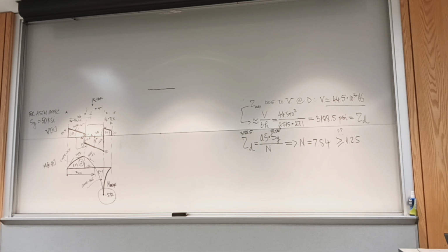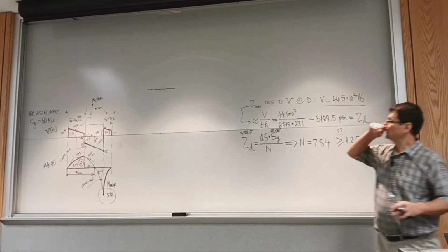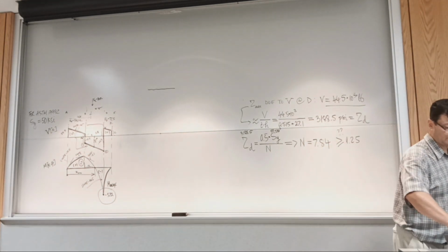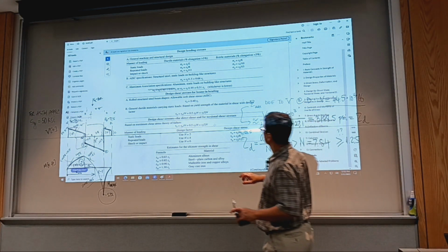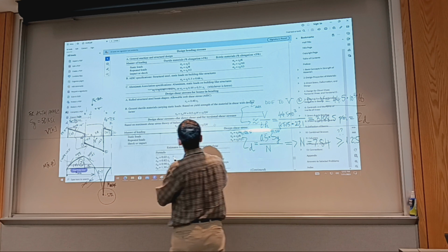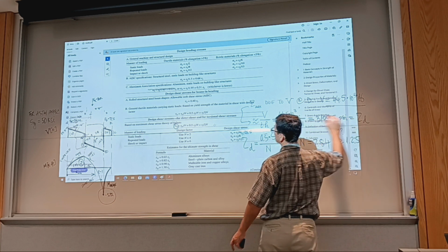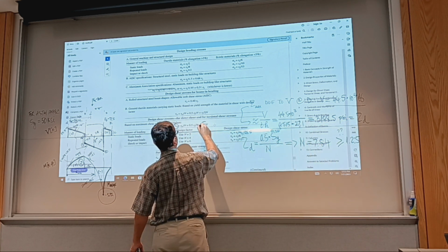So ours was structural steel, and this is the design stress for bending and for shear. For direct shear and for torsion shear stresses, this is the equation. So I made use of this equation. Oh, I'm not projecting. Come on, projector. All right, so design shear stress, direct shear, and for torsion. Ours will be of the direct shear type. We evaluated the design shear stress, and then I used this equation.